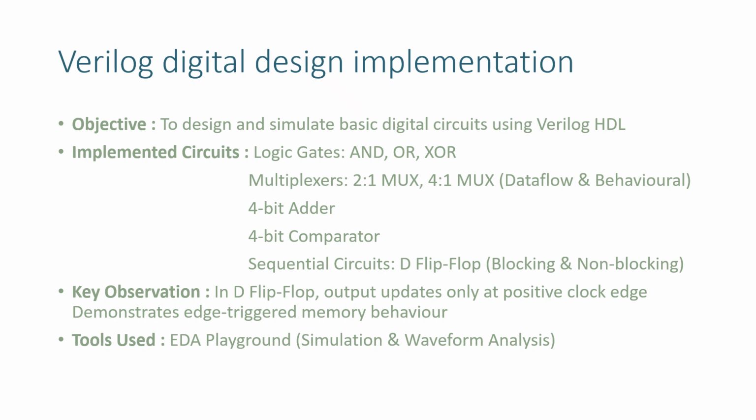For sequential circuits, I designed a D flip-flop using both blocking and non-blocking assignment. From the waveform analysis, I observed that the D flip-flop output changes only at the positive edge of the clock, which confirms its edge-triggered behavior and memory property. Blocking assignment executes sequentially and updates immediately, whereas non-blocking assignment executes in parallel and updates at the end of the simulation time. All the simulations were performed using EDA Playground.